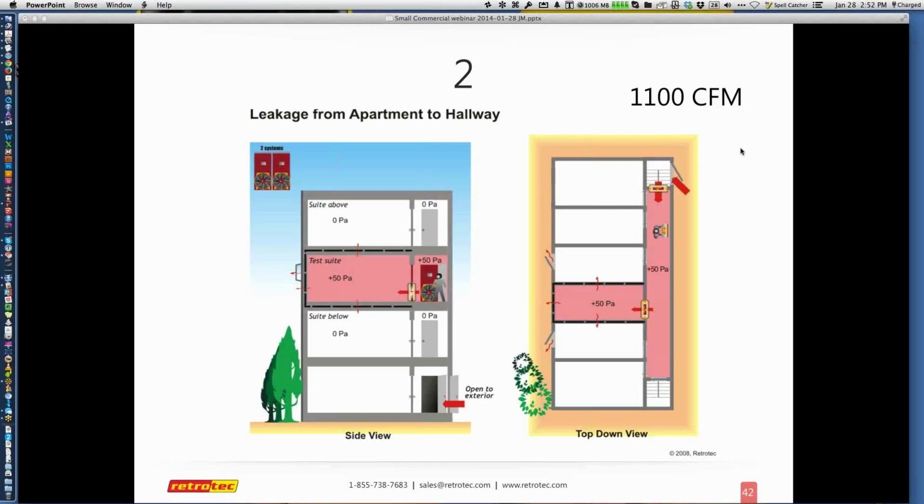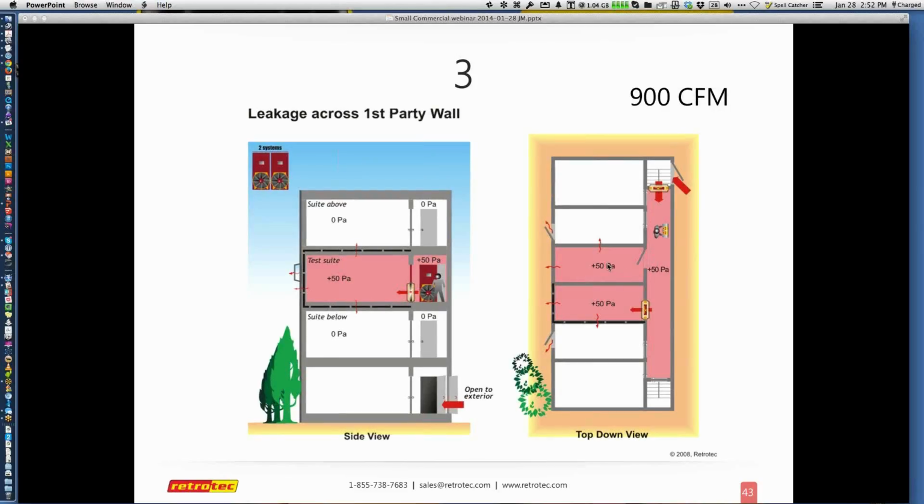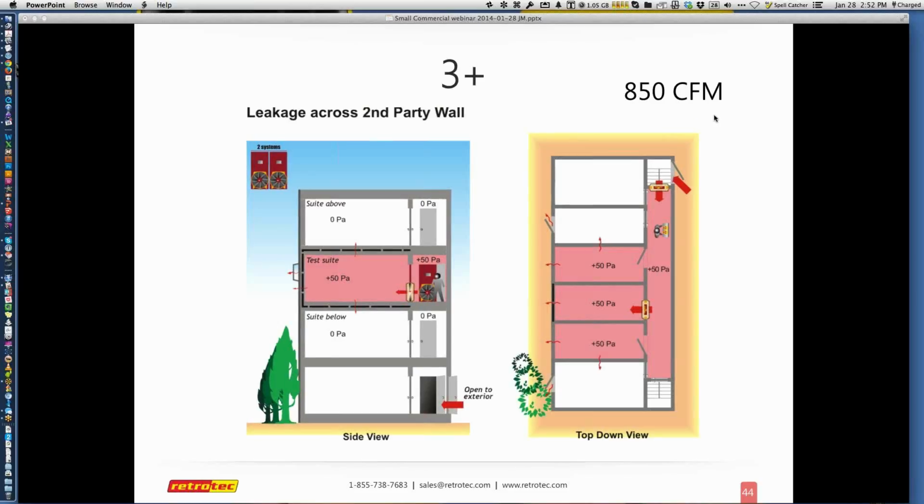And I can either open doors, if that has an application, or I can set up another fan in there. Now I start creating a neutral pressure between my main environment and the ones that are adjoining it. I can start seeing my CFM drop, and I can determine that between these two units I have 100 CFM that's connected. As I continue to the other side, the same thing happens. This one only had 50, so my larger connections were across the front or across the right side as you face the front.